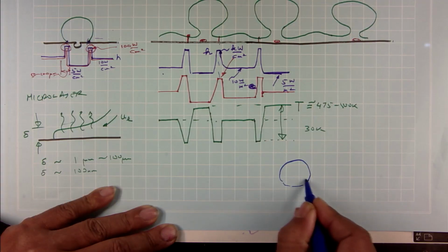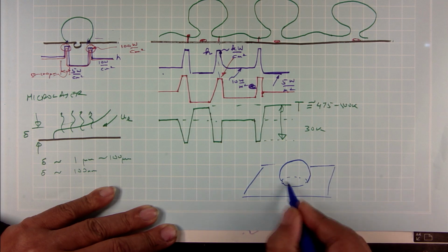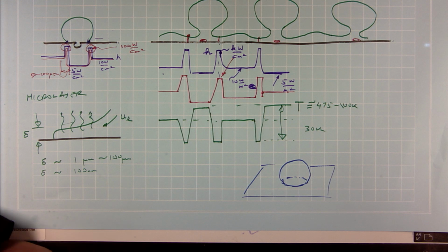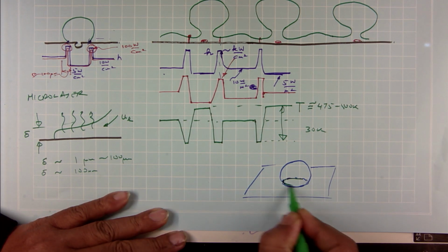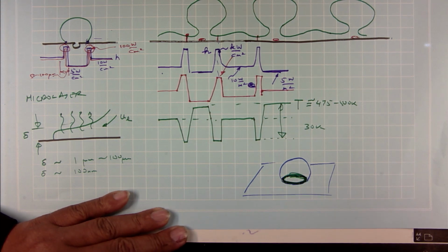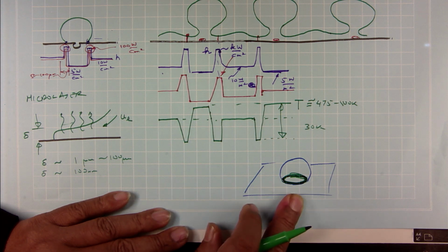Okay. So, every time I form a bubble, the bubble will have a contact on the heater surface, isn't it? So, wherever it is contacting, that is the location where I will see a cold spot. Now, what is the significance of this cold spot? More than half the total heat transfer is occurring there.